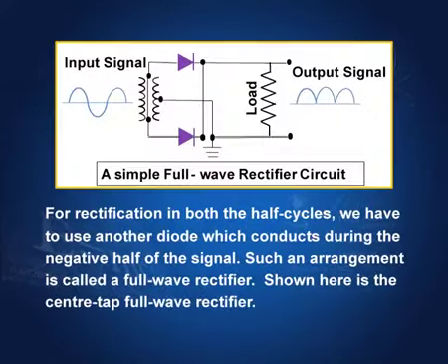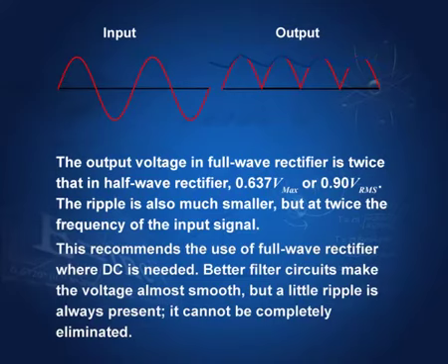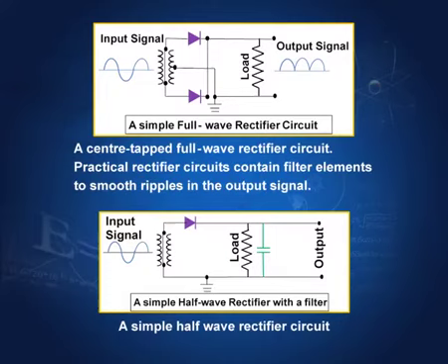The circuit is here; it is called a center tap full wave rectifier. In the positive half, this works; in the negative half, this is higher than the center tap, and therefore this works, and therefore we have output like this. And then if there is a capacitor in the output circuit, then the filtration process also takes place. This is the circuit again for the half wave rectifier, where only one diode is used, and for the full wave rectifier, two diodes are used.